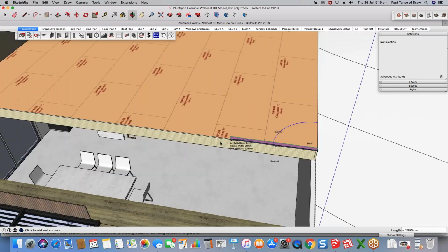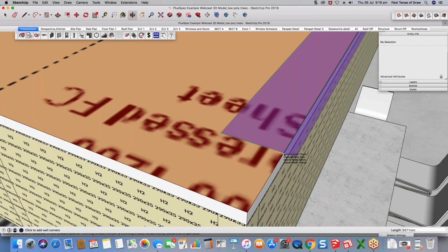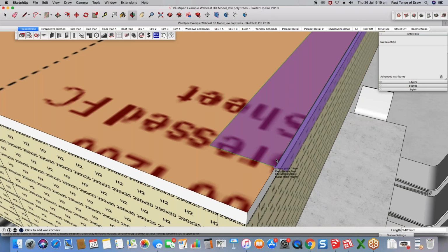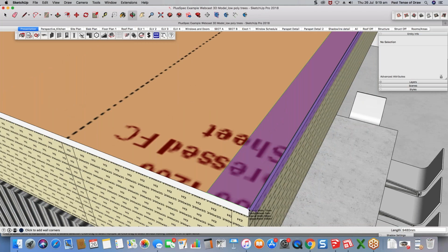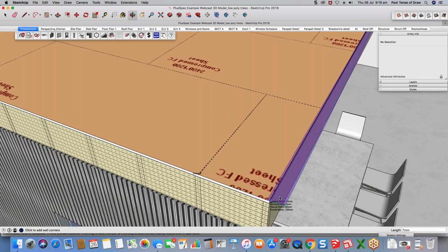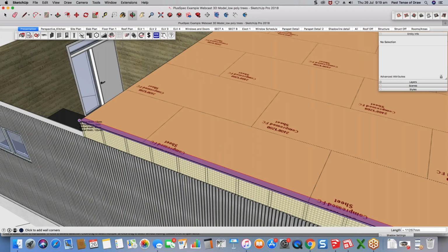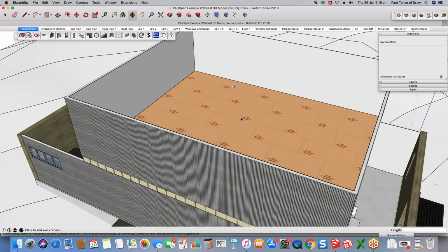But it's very important to note the alignment of your walls. Again, a lot of you I've seen are quite intermediate here, so I won't spend too long on this. But if you click on the right arrow key, it gives you the ability to toggle through the wall alignment. It's just important that in this construction detail I want it to be my finished material on the outside. So now what I can do is quickly go around and trace this basic shape. I'm keeping it very simple here. I can go around and enclose it, and now I've got this second level.